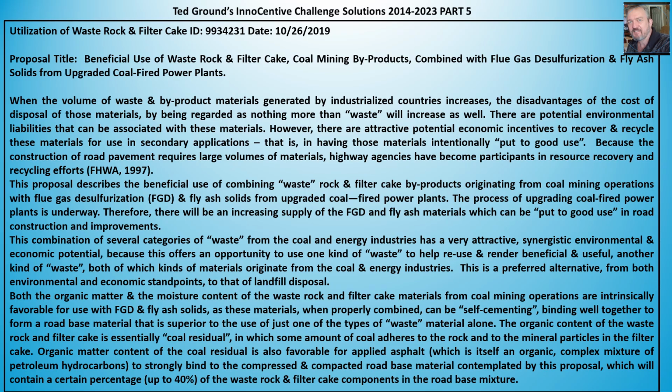The organic matter and the moisture content of the waste rock and filter cake materials from coal mining operations are intrinsically favorable for use with flue gas desulfurization waste and fly ash solids. They can bind well together to form a road-based material that is superior to the use of just one of these types of waste materials alone. So you can pause this and read the whole thing in detail, and we can move on to the next slide.